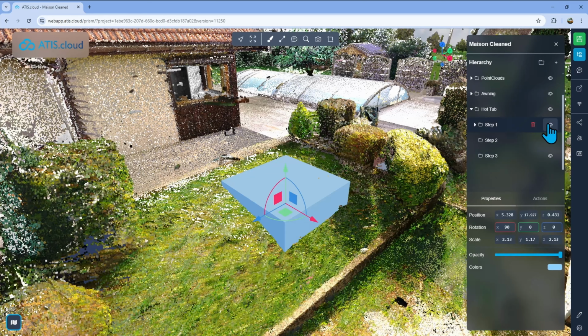Yeah, that's fine. Escape. Oh yeah, I'll actually lock it, hide the frame, put it into step 2, check C, put it into step 2, and now I have my box. In the meantime, I'll also disable all of the rest so that I'm sure that it doesn't apply on anything else, because in the future that might pose problems. So I'll just deselect everything except house here. And then what I'll do is go back into hot tub, I'll enable it, and now I'll place it according to what I currently have to make sure that it fits perfectly.